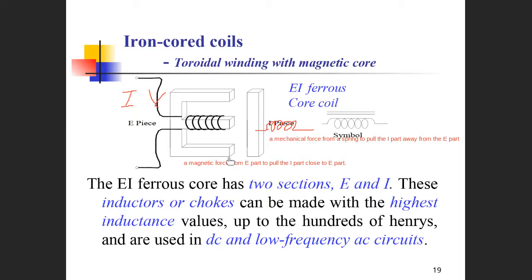Actually, this is frequently used in controlling power distribution facilities. Automatically, we can use a CT to detect the current on the facilities. If the current is small or too big, we can turn the facilities on or off by using such devices.